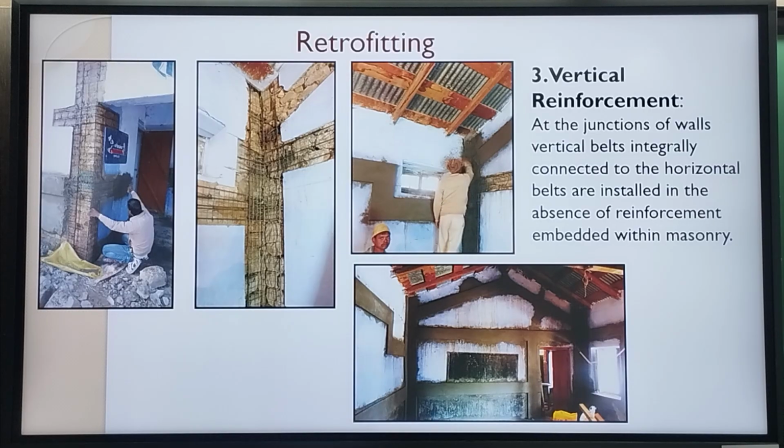And this situation requires special reinforcement, because when you have longitudinal tensile stresses, it is going to cause shear within this vertical part. So there is a special shear reinforcement that is added. I'll not go into detail of that, but it's good to know that it is possible to modify the alignment to small extents when you have this kind of opening.